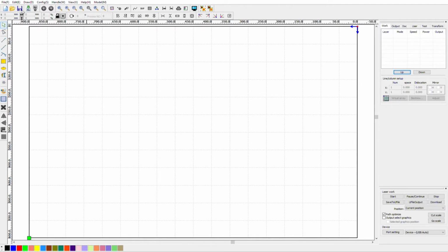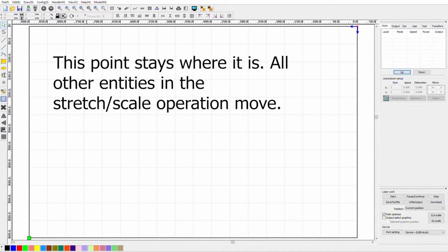The horizontal and vertical double-headed arrows indicate the magnitude of the extents of the drawing in the X and Y dimension. The percent controls our scale in X and Y, expressed as a percent. If the lock beside them is closed, they will work together. If it is unlocked, the selected entities can be scaled independently in the X and Y axes. The tic-tac-toe grid, beside the lock, controls the point that the part is scaled about.